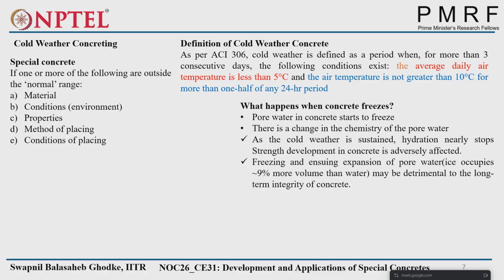So what happens when concrete freezes? We also saw the freeze-thaw effect in air entrained concrete, if you remember, right? So the pore water, whatever water is available in the concrete, starts to freeze. If it freezes, the chemical composition of the pore solution also changes. Ice occupies more space than water, about 9% more volume. There is no space already available for that amount, so what happens? It will crack, right?